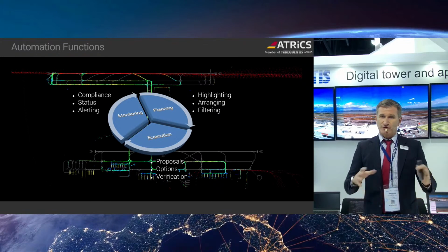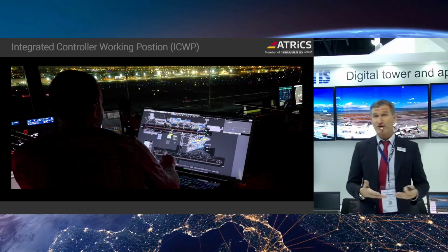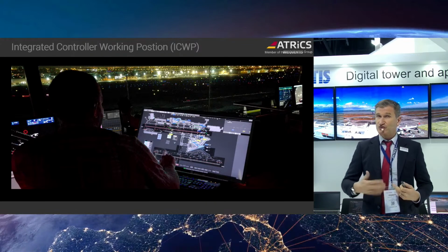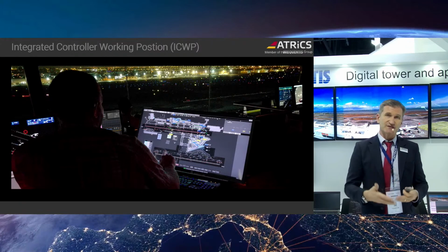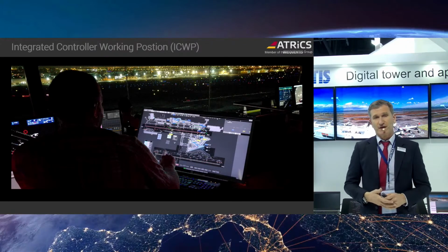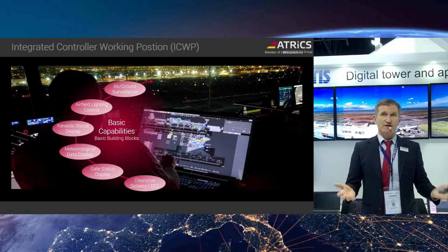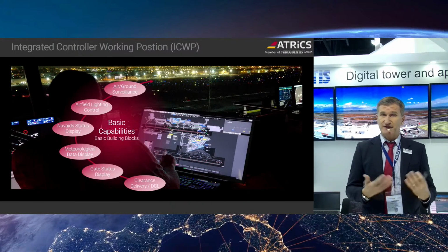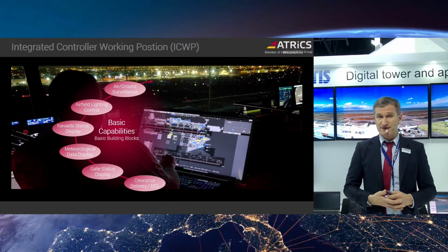So what we do is we provide all those functions on one single screen, which is then called the integrated controller working position. And as mentioned previously, it's not to overload the controller. It's to make sure they really get only that information and support those actions which are required according to the current workflow. On the one side, we provide basic capabilities. These are the traditional functions like clearance delivery, display of metadata, nav-aid status, even the manual or conventional airfield lighting control capabilities for switching intensities and all that stuff.